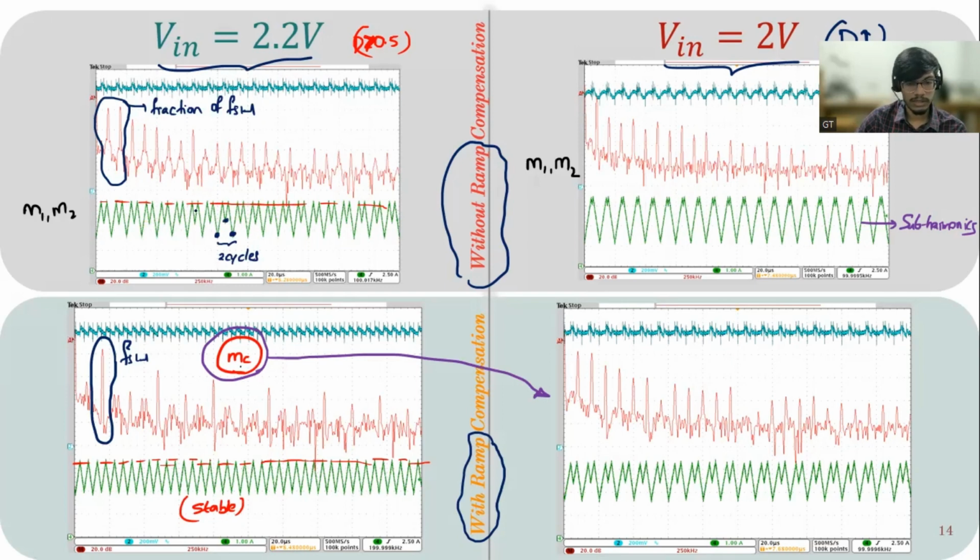Is that clear? Sir, could you please repeat it once? So let me draw it again. So the waveform was like this. So till this point, it is one switching cycle TSW, and till this point, it has one switching cycle TSW. So it has TSW time period. Also, this outer side also has time period T. So which means it has a lesser frequency harmonic component also, which is the reason for this peak. So this is a fraction of switching frequency, and this is switching frequency.